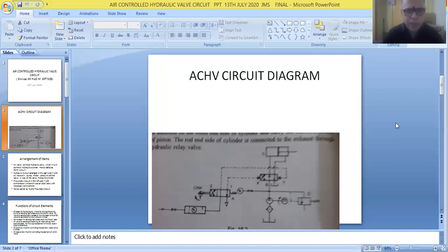And finally, coming to the air valve, we can see a mechanism that is referred to as a cam mechanism. This is used for moving the element of the air valve in forward and backward directions. The cam mechanism is used for moving the element in forward direction, and additionally a return spring is used for moving the air valve element in reverse direction.